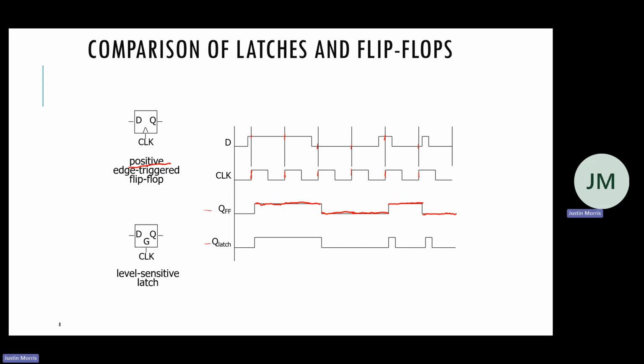The latch is a little bit different, right? For the latch, we're enabled when clock is 1, and we're transparent when clock is 1. So while the clock is 1, which is here, Q becomes what D is. The entire time, D happens to be 1. And then when the clock becomes 0, we hold the previous value, which is 1.